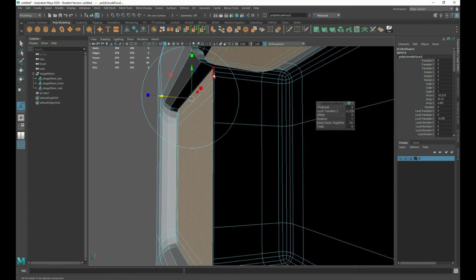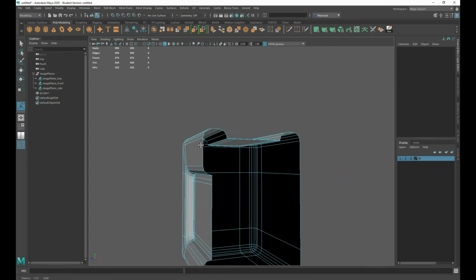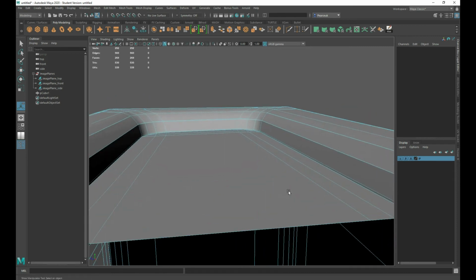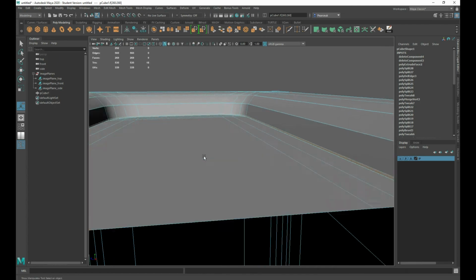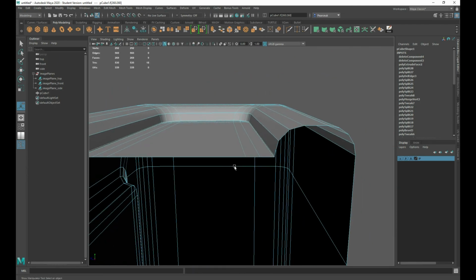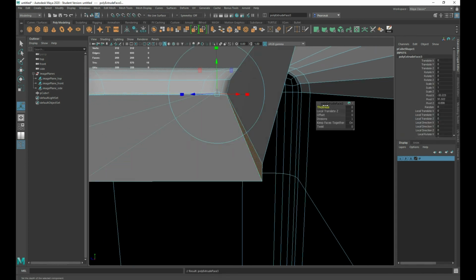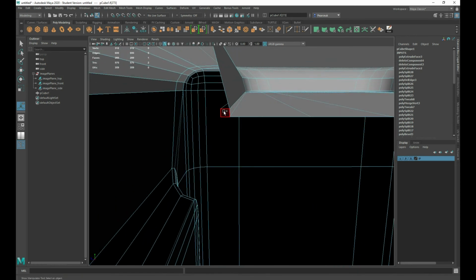And I feel like this one can be a little bit greater though, but I also want to make sure I delete these edges because we will be mirroring this in a moment. And delete. And then what I'm going to do is take that edge or that run of faces, double click the next one to select all of it. And then I'll do these separately this time because it will be slightly different. I'm going to extrude and then do the thickness negative value. And I'll go in, say 0.3. And again, I want to delete these little faces there.